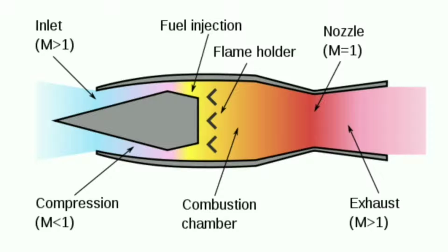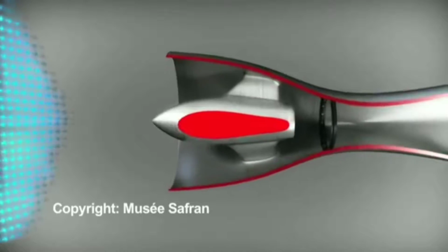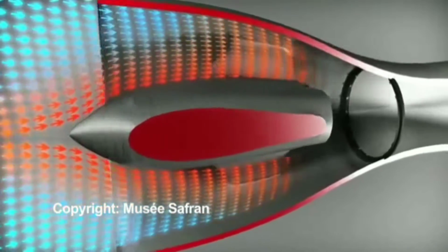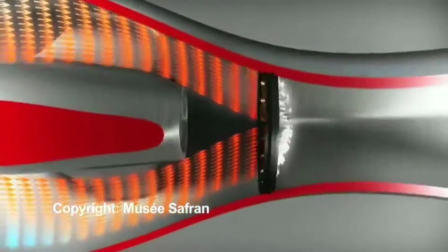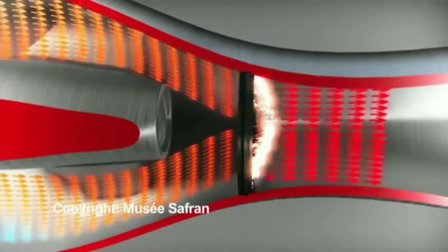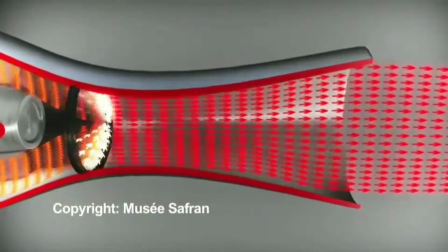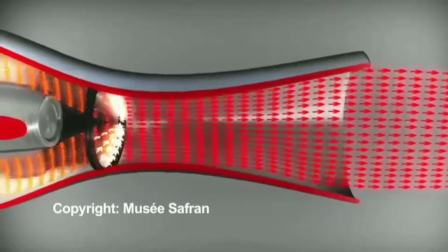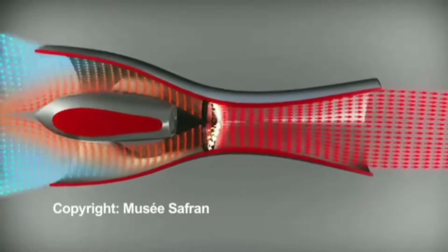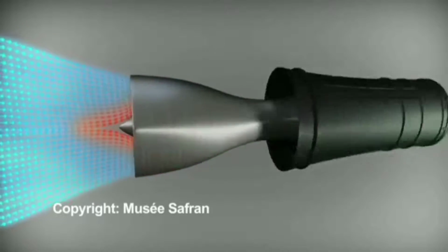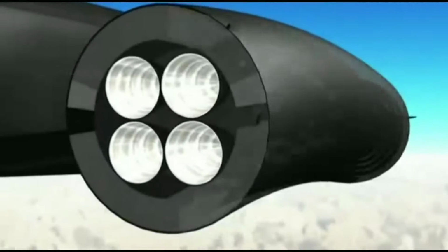A ramjet engine mainly consists of a diffuser, combustor, and a nozzle. The air entering the diffuser at supersonic flight velocity is terminated by a strong normal shock to bring the air velocity to a suitable level for the combustor. In the combustor, since there is no downstream turbine, a ramjet operates at stoichiometric fuel-air ratio for the kerosene. Overfueling the combustor results in a substantial drop in engine airflow and net thrust.